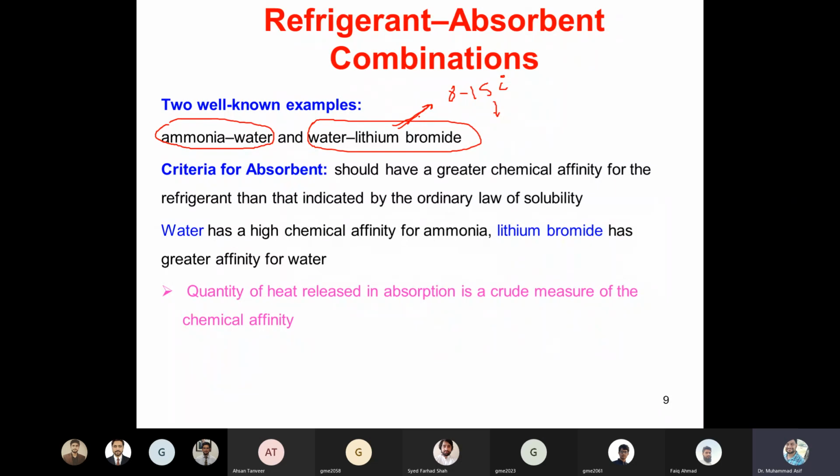So through the heat exchange with the air, the cooled air is supplied through the duct in each of the offices. The same procedure applies for the heating process, where they send the hot water from the main unit to FME in the air handling unit, where through heat exchange with the heating coil, the hot air is supplied in various offices. But we are talking about, in this application, the cooling process.